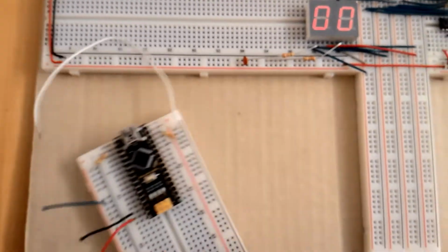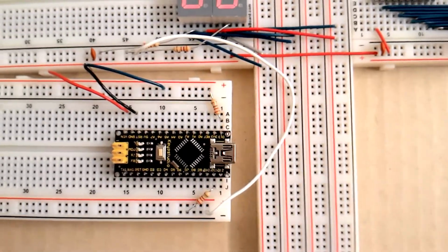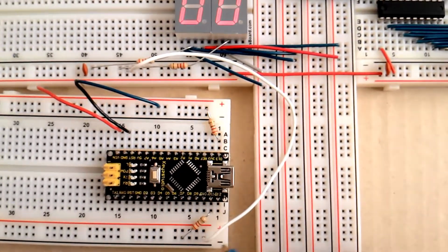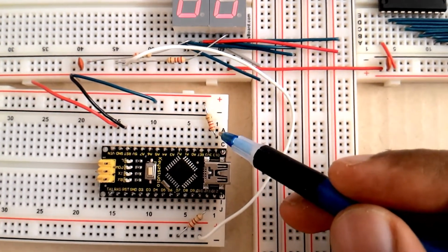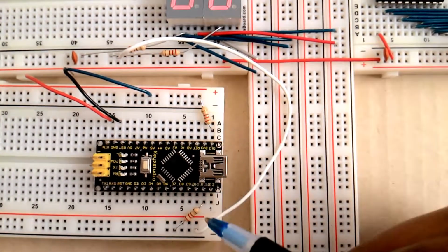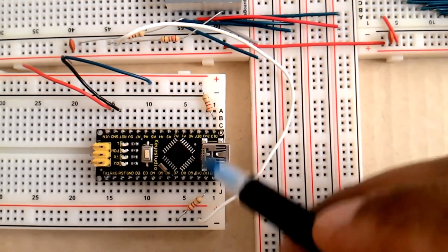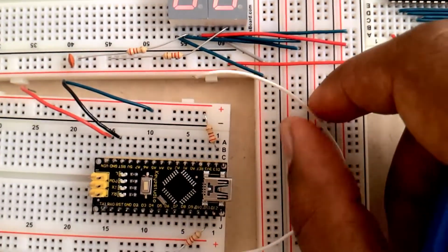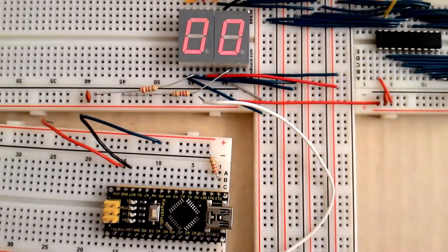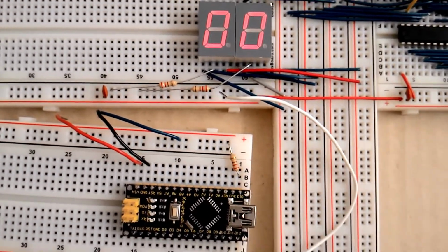And for the demo, I'm going to use an Arduino Nano, and I've programmed this Nano by alternating 2 digital pins, that is digital pin 13 over here and digital pin 11, which will give me an alternating signal like a timer circuit, and I'll connect these outputs to the display, and I'll show you how alternating displays will eventually give us a decimal value.